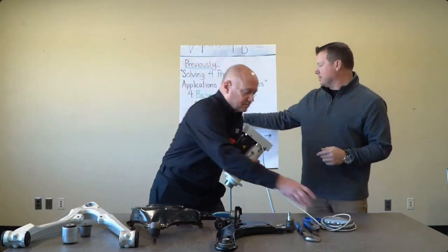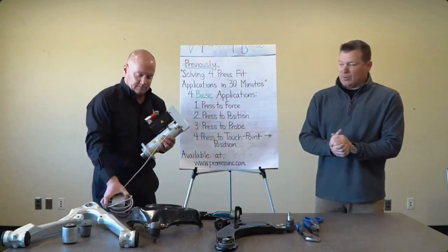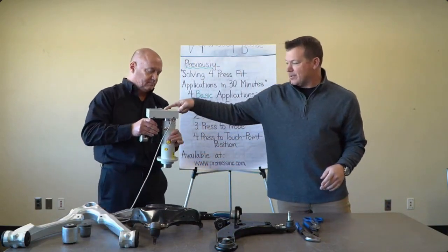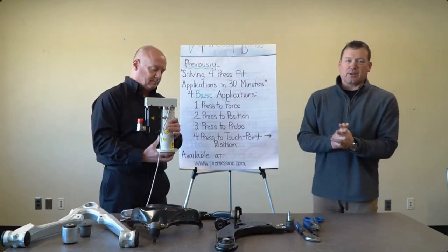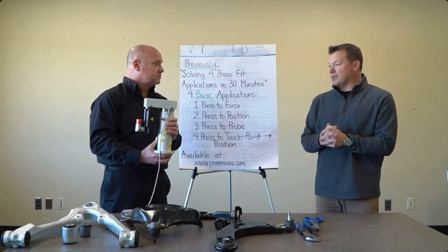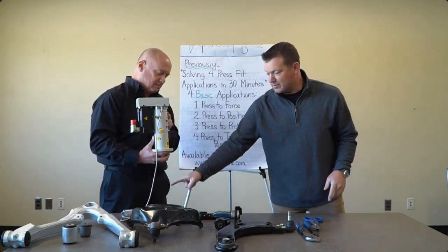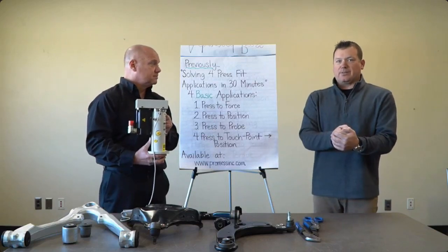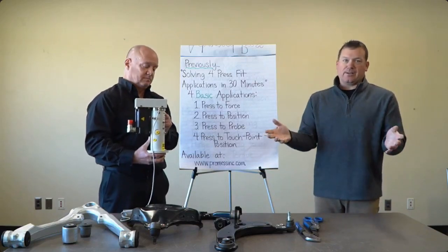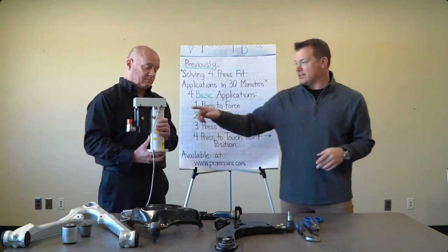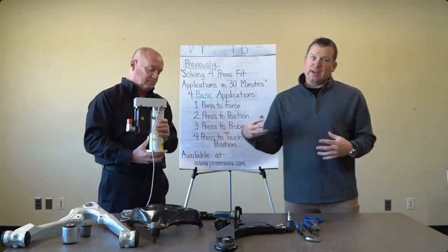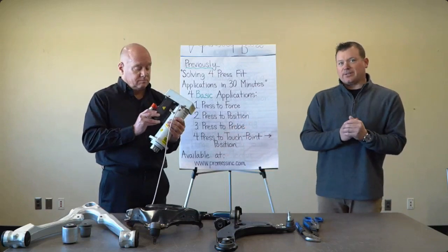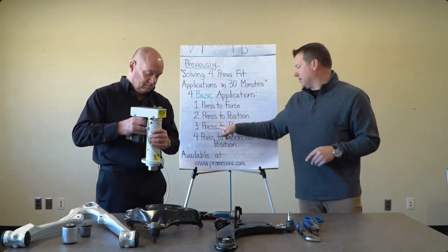But press to a position, where basically we're taking just the feedback from the servo motor, an encoder or resolver, and we're pressing to whatever we program it to press to. So as that press ram moves down and I tell it to go to 100 millimeters, it's going to press the parts together to 100 millimeters and call that done. Of course, we have all the analysis around that with the load cell and the graphing functions that our systems have. Number 3 is press to a probe.